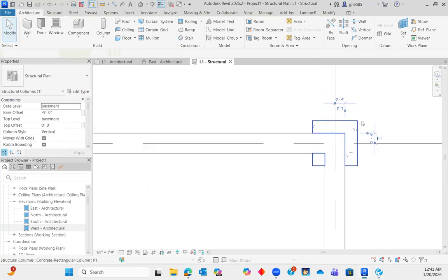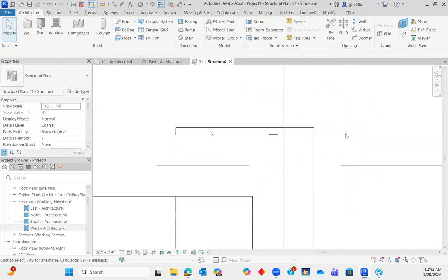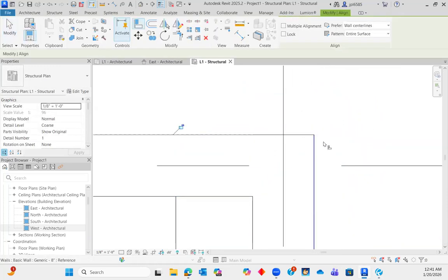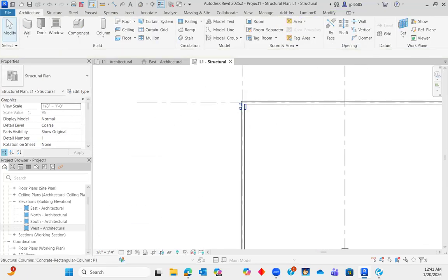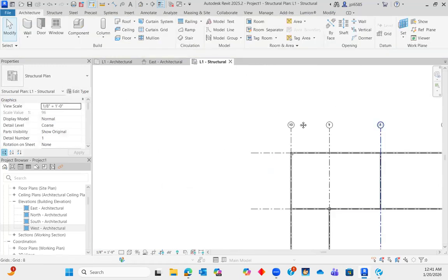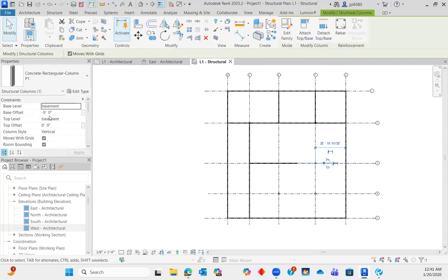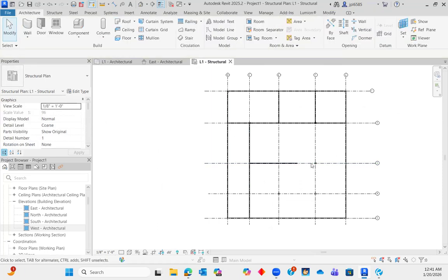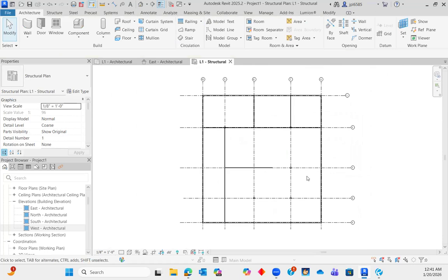So usually what I do is I just move it until the corners line up with each other. So you can use the align tool, just line up the corners, and that's usually good enough. We just want them in the general area. You're open to a little bit of approximation there. Okay, so that's how you make piers. That's how you put piers down. As always, you can adjust their offsets, etc., so that they go the correct length. So those are your piers and your foundation walls.